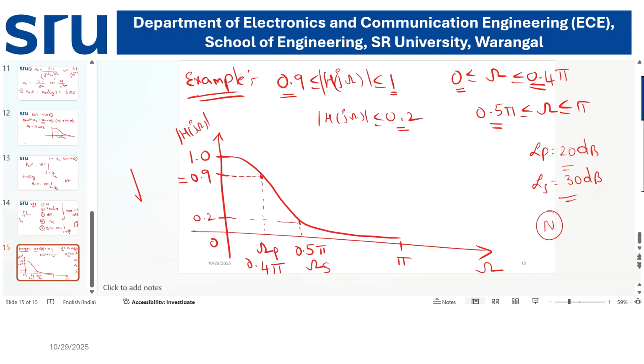From this specification we have to equate 1 by square root of 1 plus epsilon square as 0.9, and 0.2 has to be equated as 1 by square root of 1 plus epsilon lambda square. From this you will get epsilon and lambda, you get omega p and omega s. Therefore you have to use those formulas to solve and get your low pass filter or high pass filter.